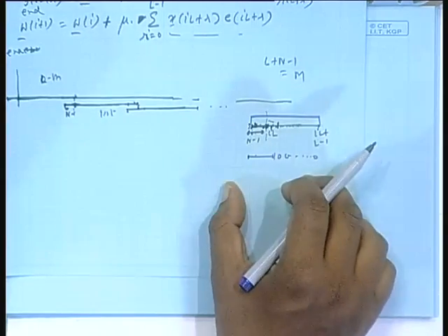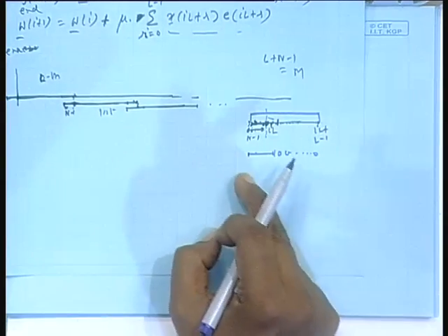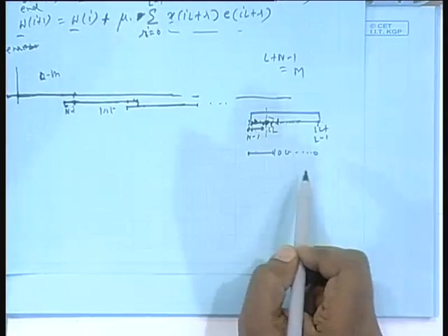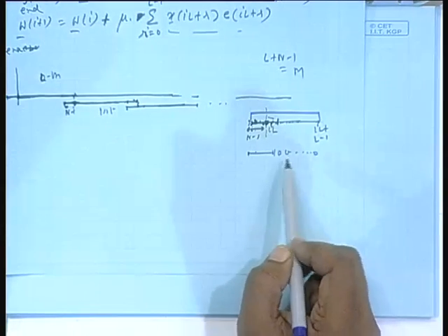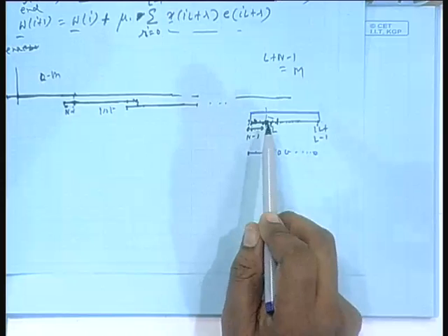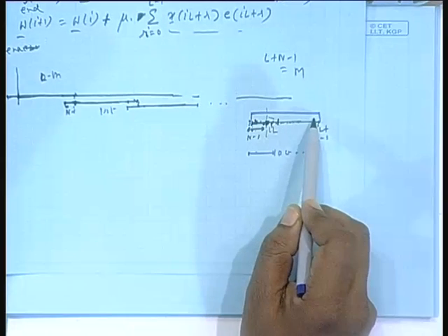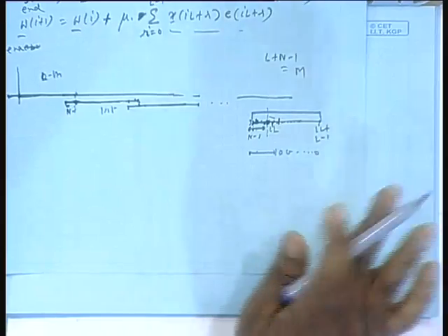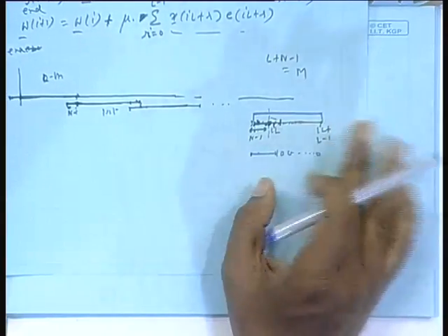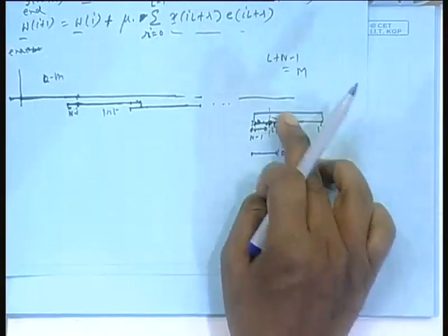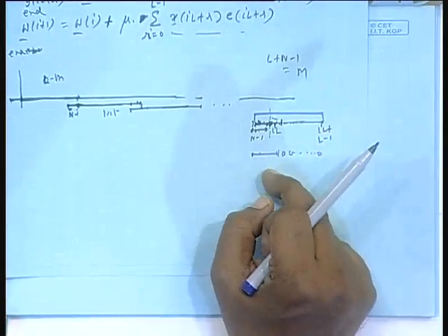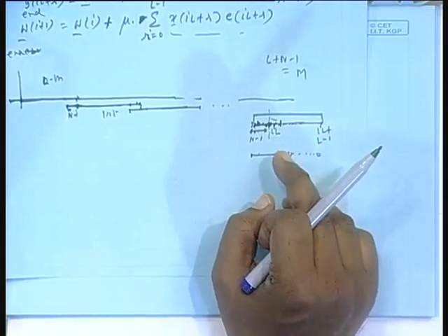Then two lengths are equal, then do circular convolution, ignore the first N minus 1, remaining ones are correct. So, that means what I have to do? This FFT I have found out. Suppose by hook or crook I know this vector and its FFT is known somewhere, then the two DFTs will be multiplied and I have to take inverse DFT, ignore the first N minus 1 samples. That is the filtering part.